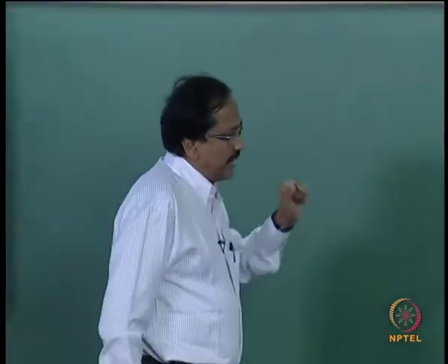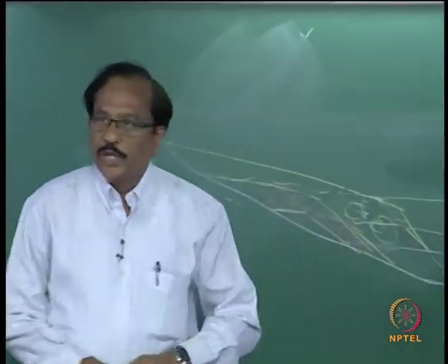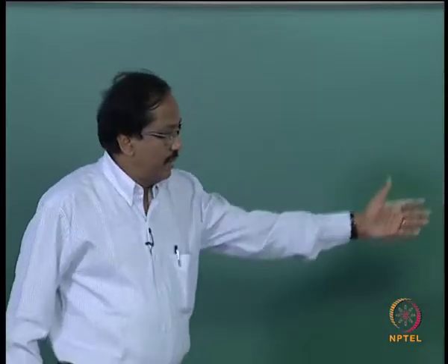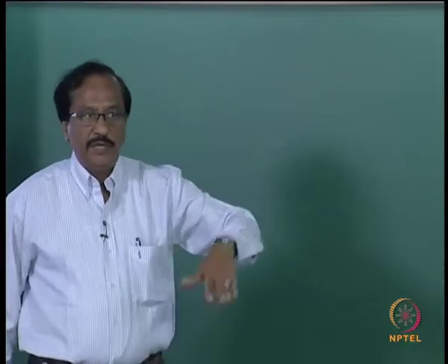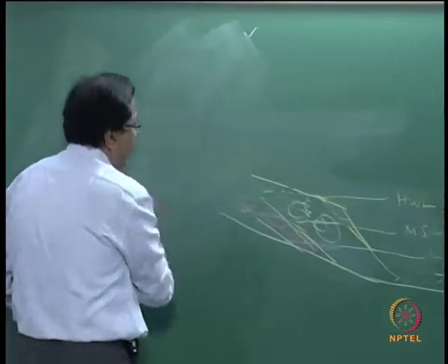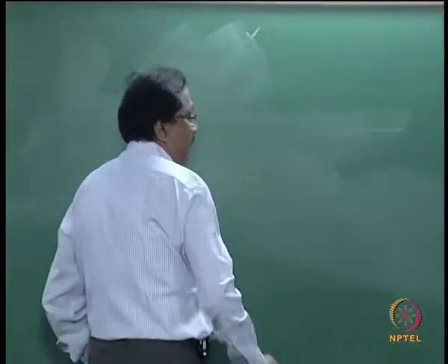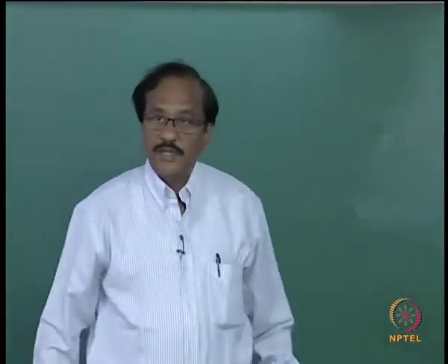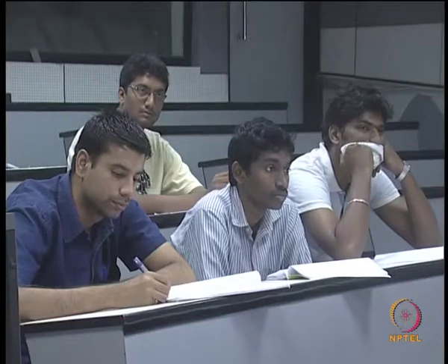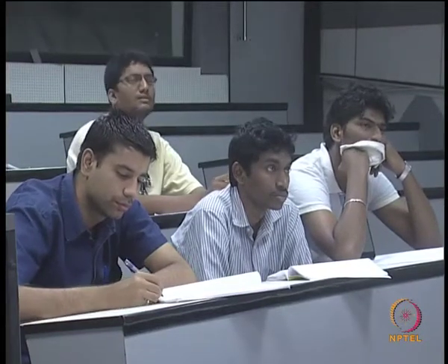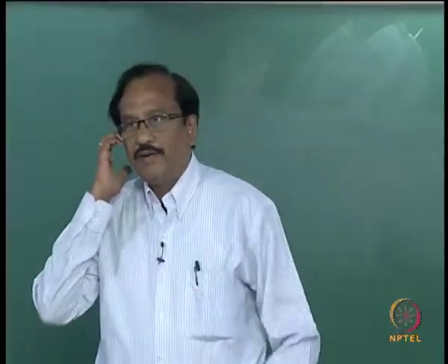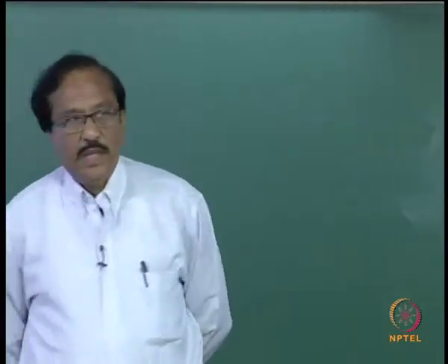So, these are some of the concepts which need to be looked into. Before you plan for a groin, it is quite important that you look at the suspended sediment transport as well as the bed load. So, this is as explained. Are there any doubts now? Now, permeable or impermeable. You know the meaning of permeable or impermeable.